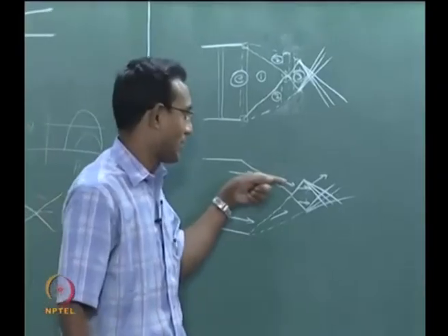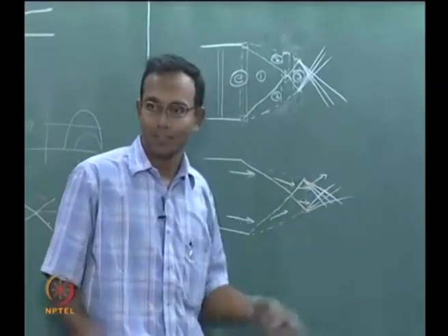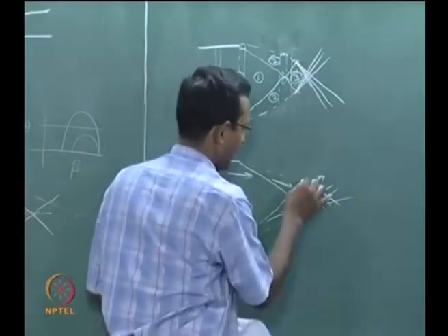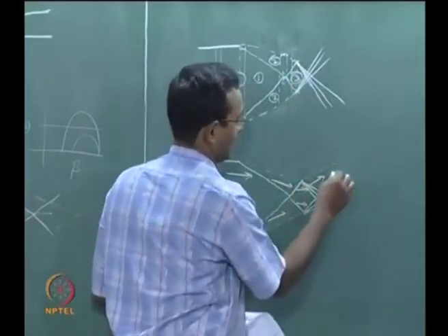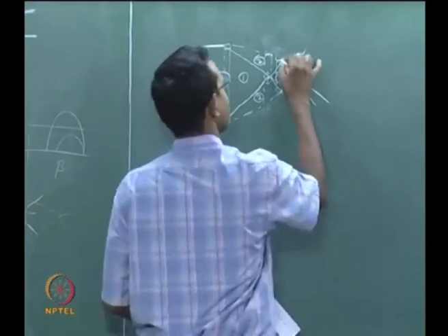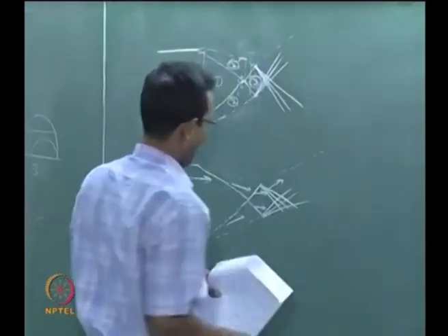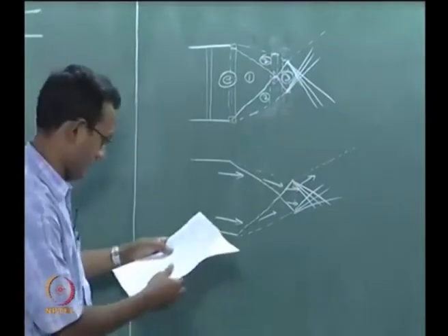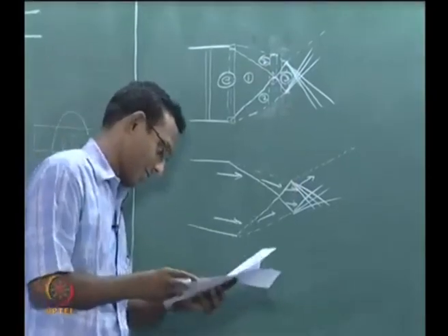Of course, you know expansion also adds some velocity vector component, so it is going to turn out. Because of that my jet boundary is going to increase again. I am not drawing both the pictures exactly the same, but you understand the idea. I have not drawn the same expansion angles.